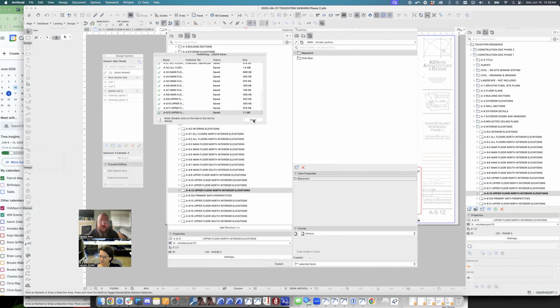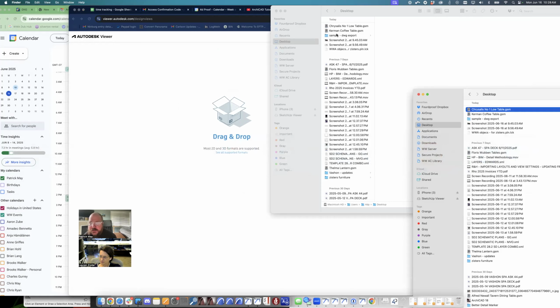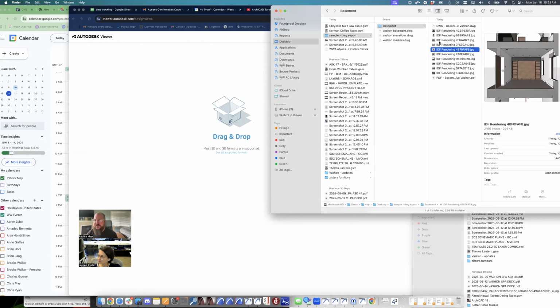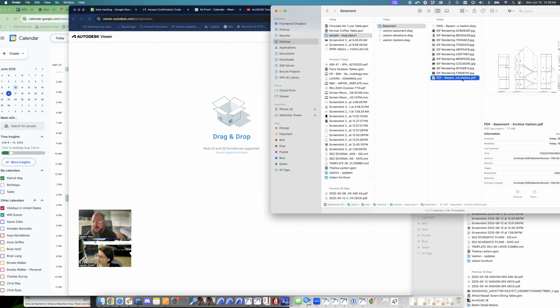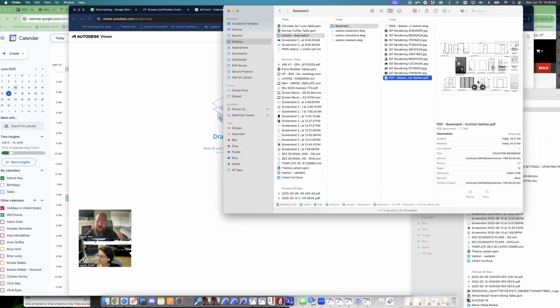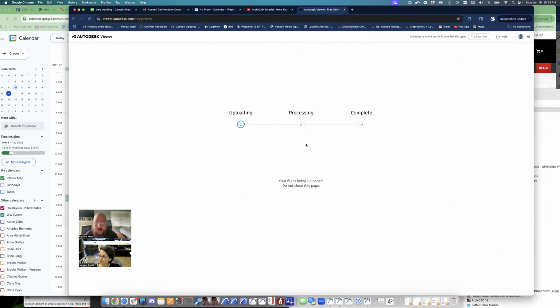saved. So we'll close that. And now if we come back into our viewer here and find the DWG export. There were images on those, so those come out separately, but here's that DWG. And then here's that PDF. So basically this is the legend, the key for what those elevations should look like. And if we open this up here and process this, this is what it will look like. Basically, it just lines all of the elevations up into a single row. So there's no drawing titles or anything. They'll have to sort of piece it together.